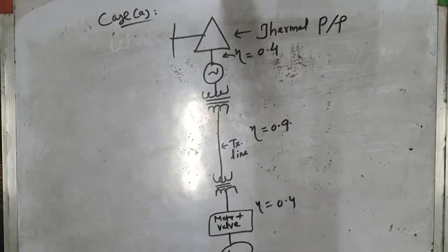And then this is the pump. The efficiency of pump is 75%, 0.75. Let us suppose the output power of the pump is 10 kilowatts. I mean, you need a power of 10 kilowatts to run this motor driven pump for pumping the water.